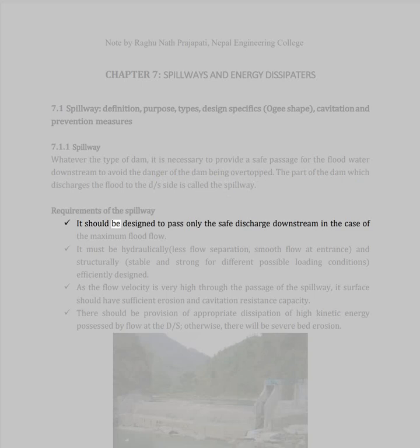Requirements of the spillway: it should be designed to pass only the safe discharge downstream in the case of the maximum flood flow. It must be hydraulically efficient, with less flow separation and smooth flow at entrance, and structurally stable and strong for different possible loading conditions.